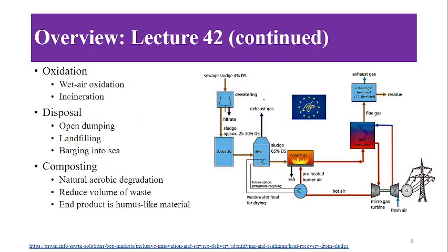Next, oxidation was discussed, in which wet air oxidation and incineration were discussed, followed by the disposal of this sludge. So now you have treated the sludge. How do you dispose of it? Either you can go for open dumping, you can go for landfilling, or barging it to the sea. One more method which was discussed was composting.